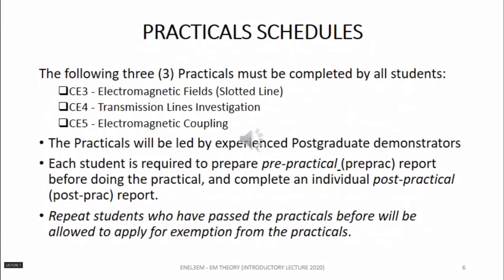Thereafter, we'll also determine the reflection coefficient. Any load that is different from the characteristic impedance of the line results in reflection of a portion of the transmitted signal backwards towards the transmitter. So we'll want to determine the reflection coefficient gamma. And finally, we'll try to determine the load impedance in each case, ZL. We can determine the load impedance by using the parameters of the slotted line.